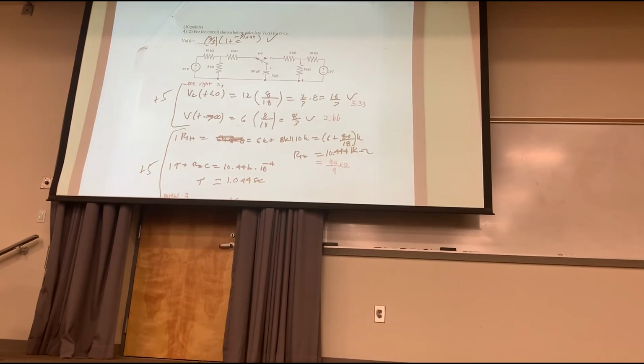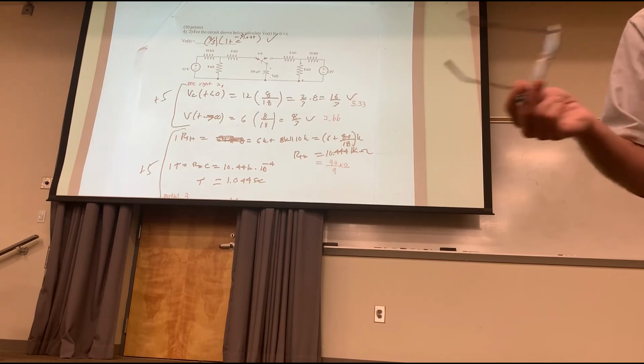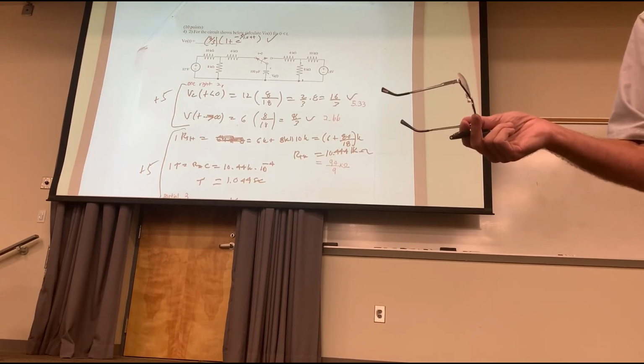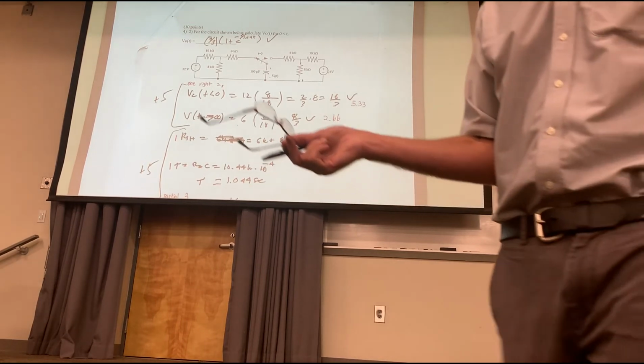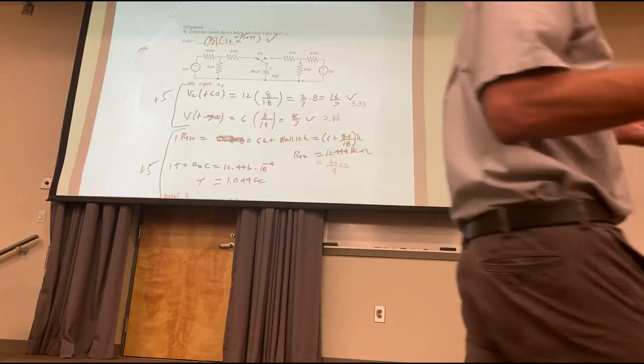I look at this, and for t less than 0 it is the voltage. Now it's voltage, not current, right? You're going to see this again. When I'm talking about a capacitor, what does it look like for all time less than 0? Open circuit, right? There's nothing there. It's an open circuit, an infinite resistance. So with that in mind, no current can flow through it.